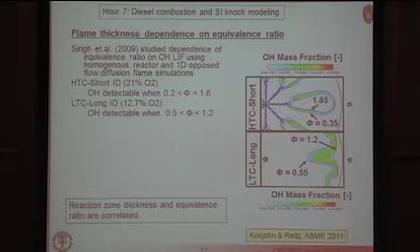If we look at the low temperature combustion case, we see that we have richer mixtures in the central region of the jet, leaner mixtures obviously outside of that region where there's more air available. And again, the OH concentration indicates the magnitude of the equivalence ratio.